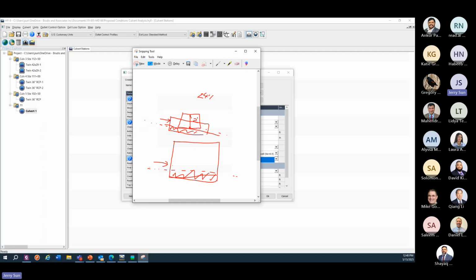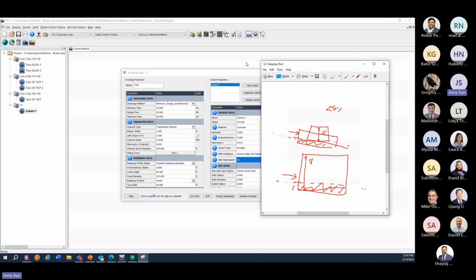So they lower it. For example, this 8-foot box culvert is embedded 1 foot, and the bottom is a natural channel. Then the fish can go through, with no change of water, bottom soil type, whatever, the stream bed. That's why sometimes they use the embedded culvert.